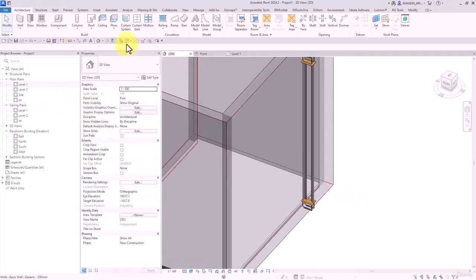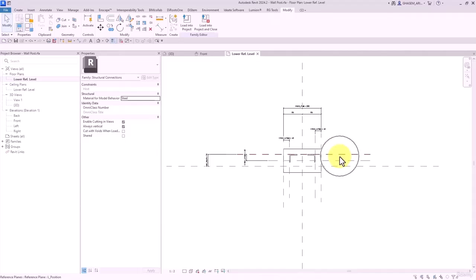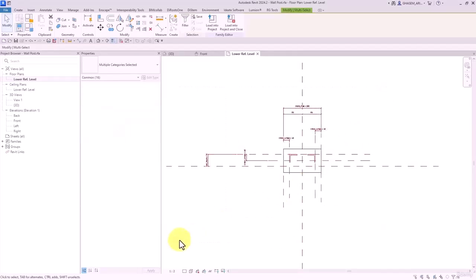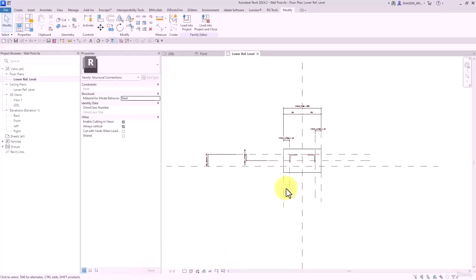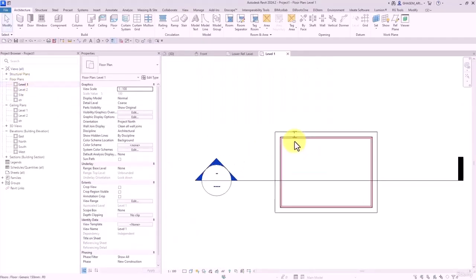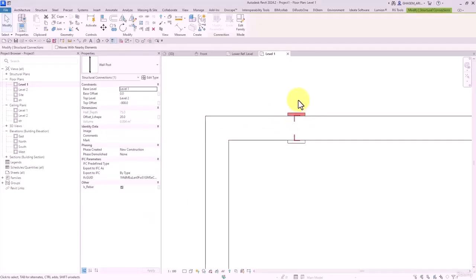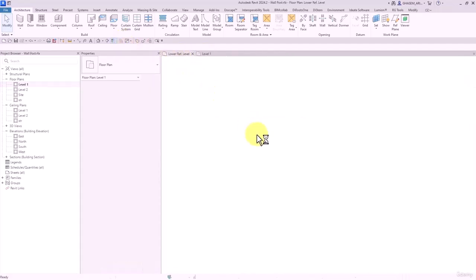Now, so far it's good, but there are some grips here at the middle which are a little annoying. What are the grips? As you can see, these are the references. I select all of them, then here I change it to reference plane. Here is reference, all of them not a reference in the last file. Now I load it again, here in the plan, select, then as you can see they're not visible anymore. So that was another point which can be really helpful.